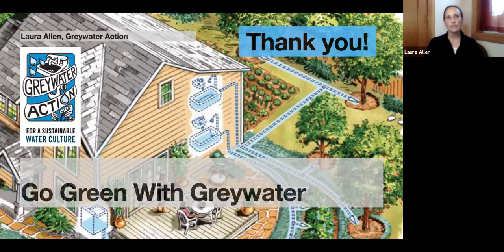For your municipality, they might clean the water. It's going to be treated sewage water, so it's all the water together, cleaned to irrigation quality. Now it's used on parks and big areas. It comes back in a purple pipe and goes to irrigate. It's called recycled water, so that's more than gray water. It's actually cleaned, the combined wastewater. And that's good, it's reusing the water. But again, it takes a lot of resources, chemicals, energy, money to do that.